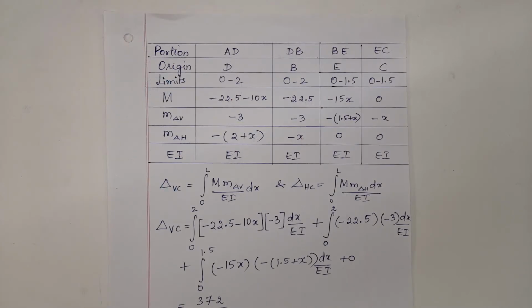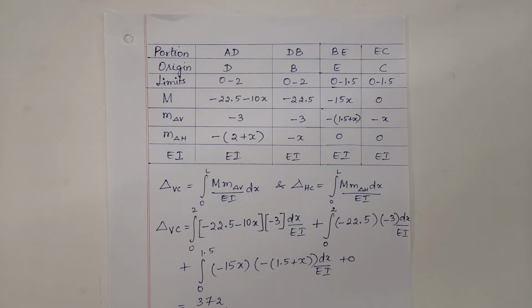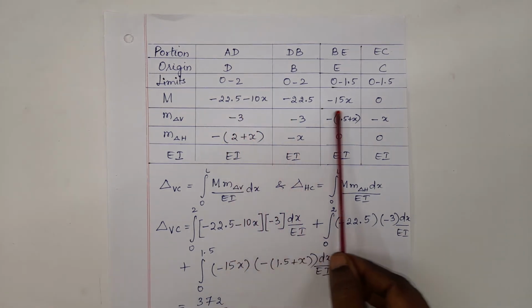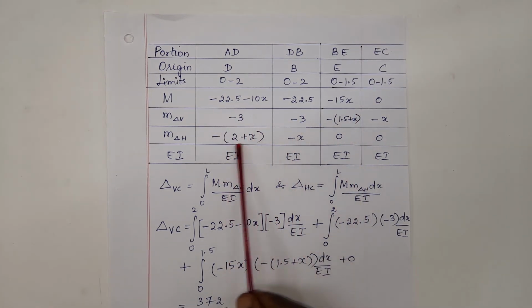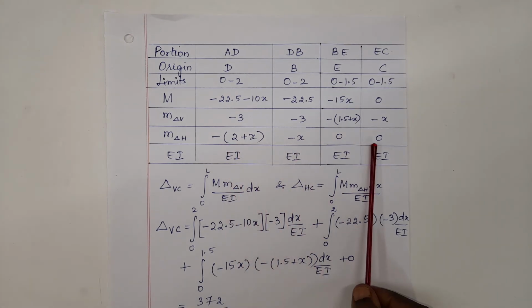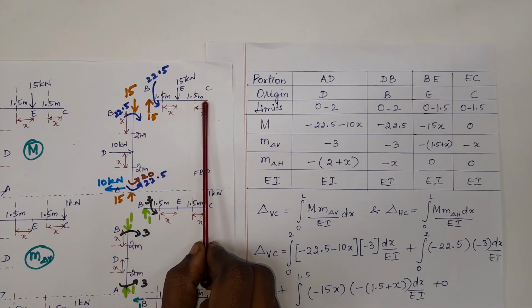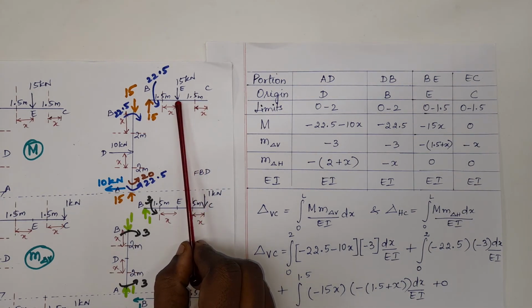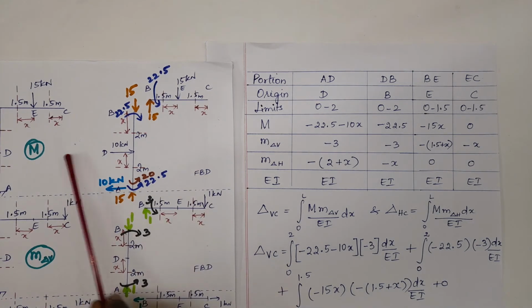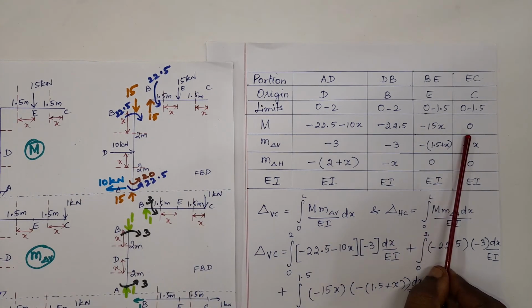Pushing the column inside and beam inside is taken as positive bending moment. So depending on that, the moment expressions are written in all the 3 diagrams where we have drawn the free body diagram. Let me explain for one. Let us check the first diagram. Starting from C up till E, there is no loading. My capital M expression turns out to be 0.